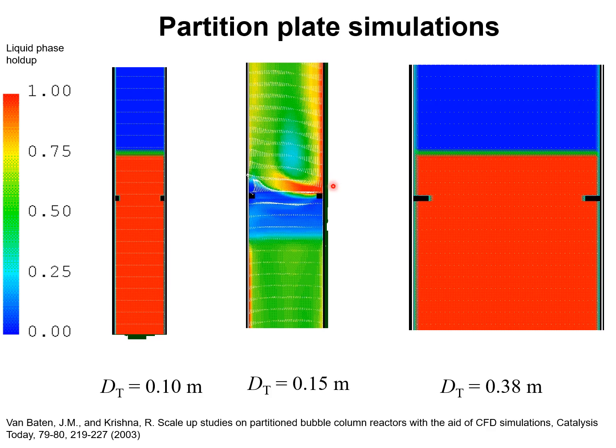But you will see here again a red region indicating liquid downflow. Remember, in the context of the soaker vessel, liquid downflow near the walls would lead to coke deposition on the walls, as is observed in industrial practice. So the introduction of sieve plate partition plates would certainly reduce the degree of back mixing, because each compartment corresponds to one well mixed vessel.